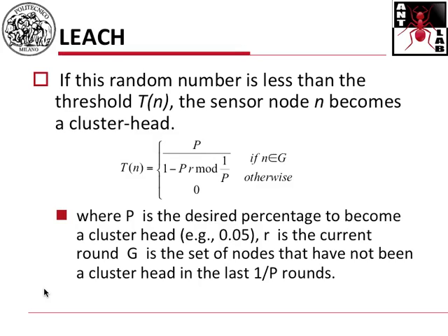The lower your energy, the lower your threshold. So basically, the hacking would be just to multiply this threshold through some kind of linear function of the remaining power, properly scaled down by some factor to bring it back to between 0 and 1, right? So I was just anticipating some drawbacks of LEACH, because LEACH assumes to be working on uniform topologies, both from the network point of view and from the battery point of view.